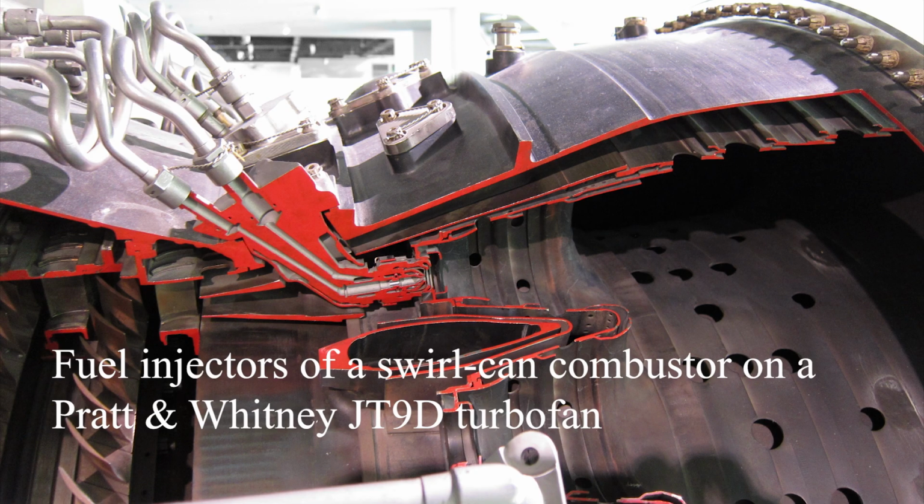However, the vaporizer tube may have serious durability problems with low fuel flow within it, as the fuel inside of the tube protects the tube from the combustion heat. The premixing or pre-vaporizing injectors work by mixing or vaporizing the fuel before it reaches the combustion zone. This method allows the fuel to be very uniformly mixed with the air, reducing emissions from the engine. One disadvantage of this method is that fuel may auto-ignite or combust before the fuel-air mixture reaches the combustion zone. If this happens, the combustor can be seriously damaged.